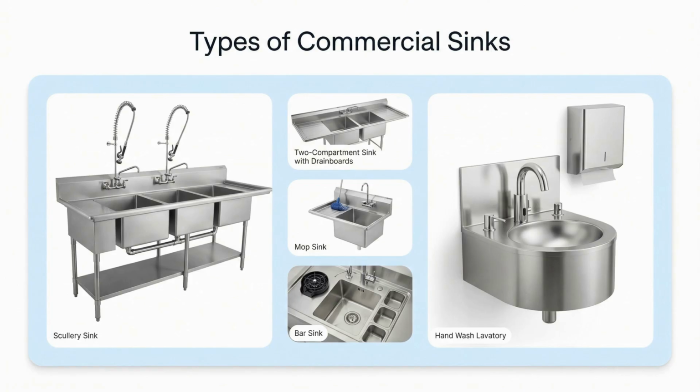Sinks, for example, are often made of stainless steel because it's durable and can be shaped for specific duties. It's important to pay attention to faucet and drain locations during rough-in. Also, remember that concealed overflows are not allowed on food preparation sinks, according to the National Plumbing Code.